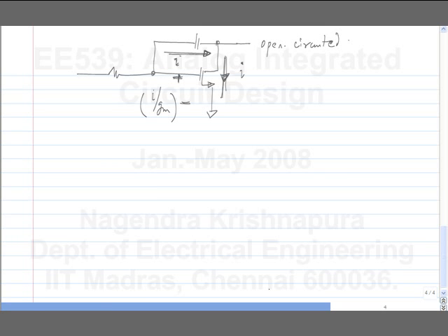Exactly what happens in an op-amp or in any high gain feedback network. So here you can also think of this as a forward amplifier without CGD, and CGD as being connected in feedback. If the gain of the forward amplifier is very large, the gain is independent of the forward amplifier's gain. So this behaves approximately like an integrator whose unity gain frequency is GS by CGD.